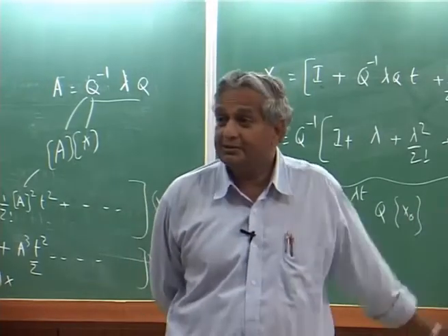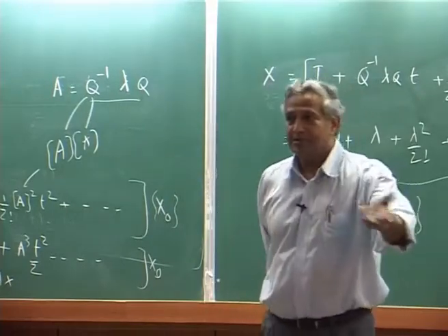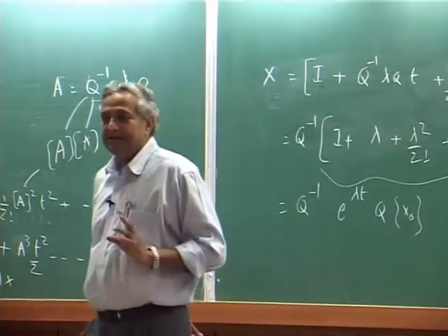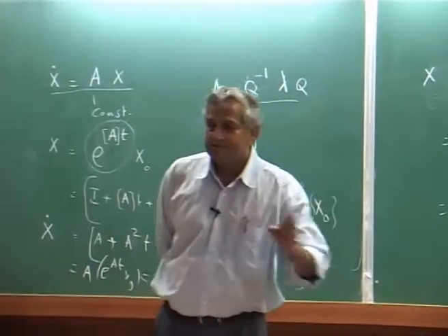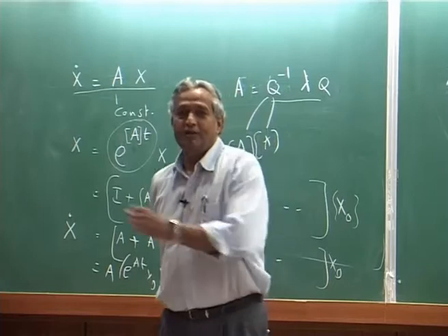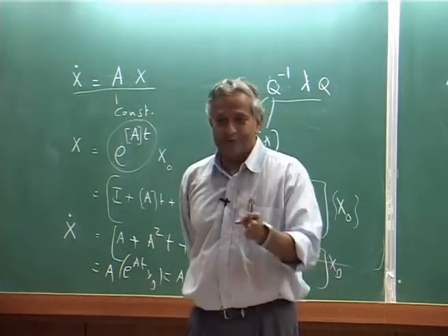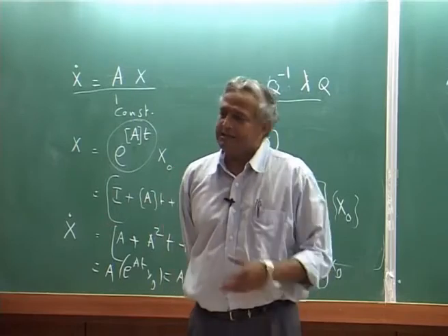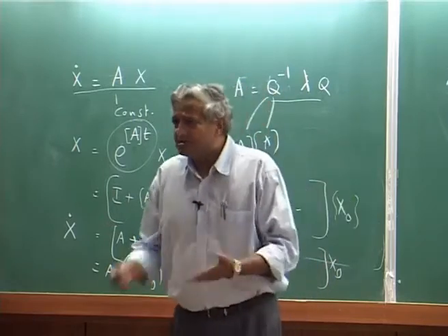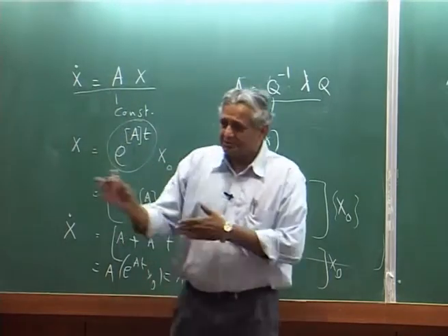So, you get the roots, and those roots essentially tell you whether the system is stable or not, and if it is stable, how much stable, or if it is unstable, how far it is unstable in the root locus. Now, you know why root locus is used, and then you want to change the system, because now you say I go change my system A, so that I make it stable.